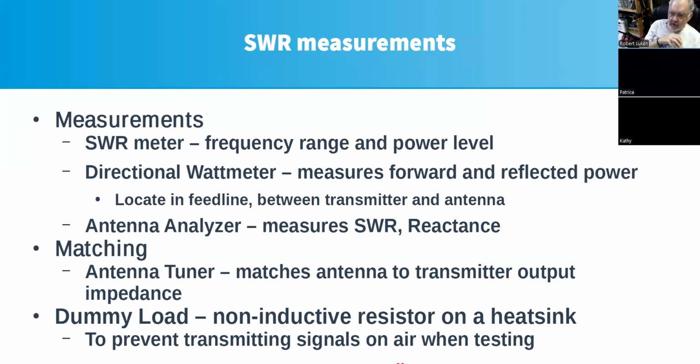So even though you have a 50 ohm feed line, if the antenna is, say, 200 ohms, you're going to see more like 200 ohms on the radio end of that feed line. So that's what that tuner function does, is try to make an impedance match between the radio and what it's seeing on the feed line.